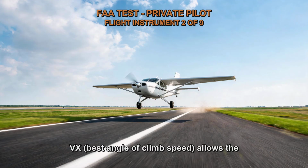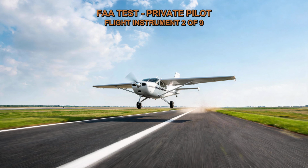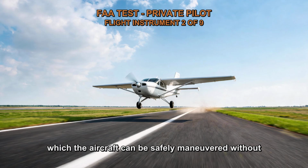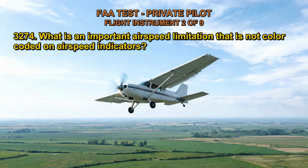Vx, best angle of climb speed, allows the aircraft to achieve the steepest climb angle and gain the most altitude in the shortest horizontal distance. However, Vy provides a higher rate of climb and is more effective for gaining altitude in a given period of time. Va, maneuvering speed, is the maximum speed at which the aircraft can be safely maneuvered without exceeding its structural limitations. It is not directly related to the climb performance or the rate of altitude gain.